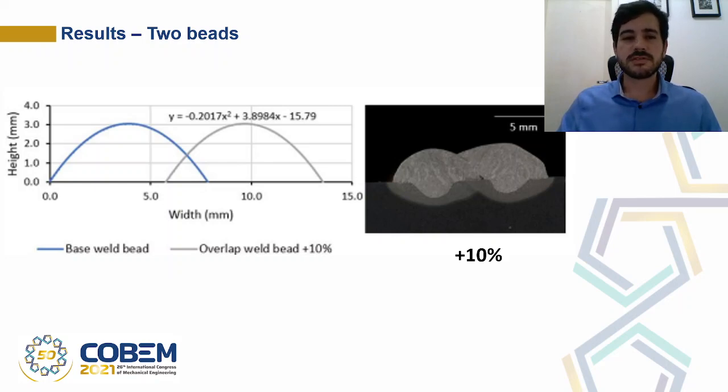Analyzing the proposed method, it was verified a good approximation between the simulation and experiments, with error less than 1% for width and 2% for height. However, for a good weld quality, it was necessary a reduction of 10% in the center distance. In general, the optimal center distance calculated using the proposed method corroborated with similar works referred to in this paper, that also found center distance values around 67% to 73% of the base width. This shows that it's possible to accurately and precisely use second degree functions to represent weld seams, even though in some real cases the overlap bead height may vary somewhat.